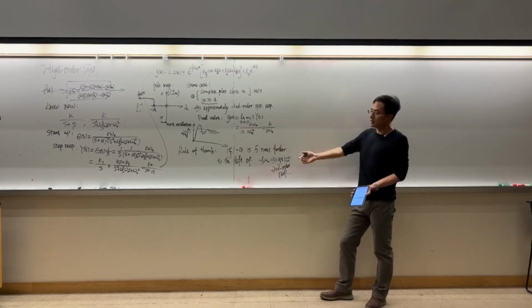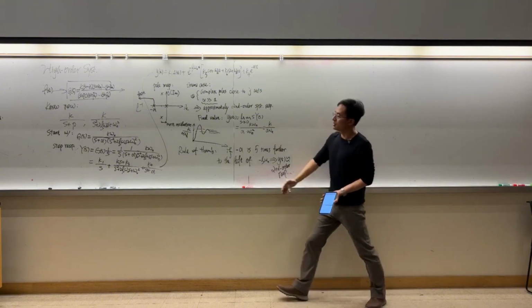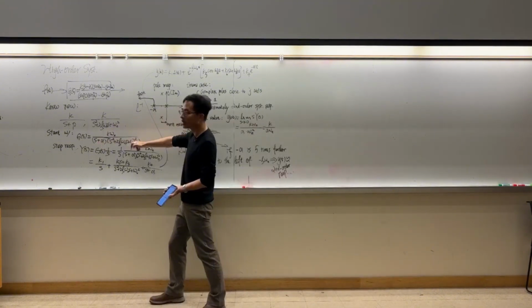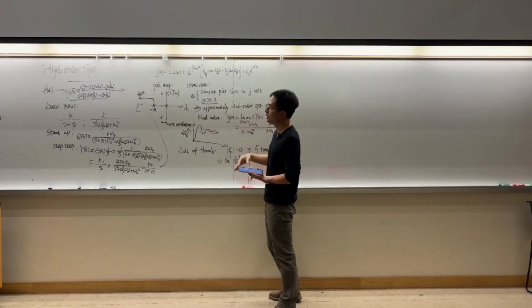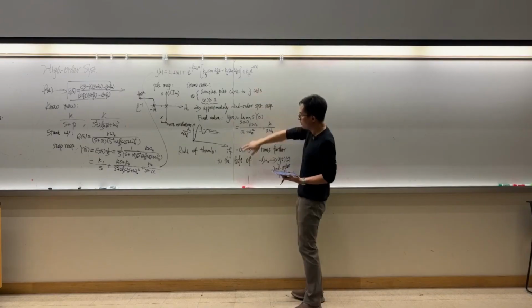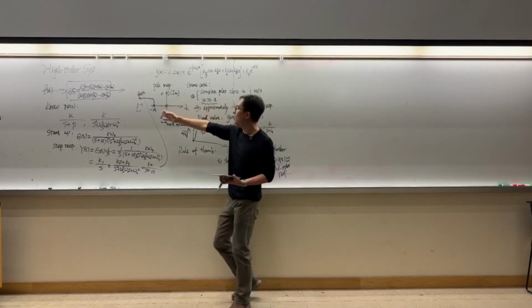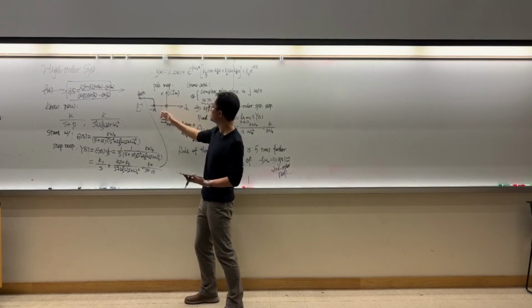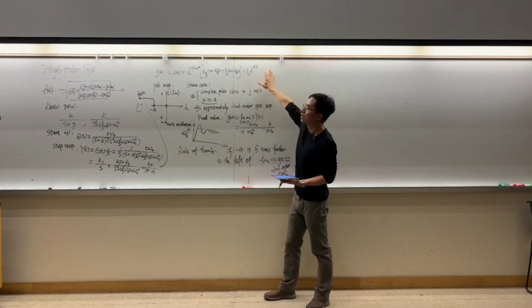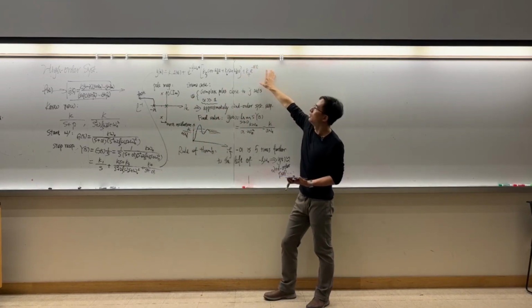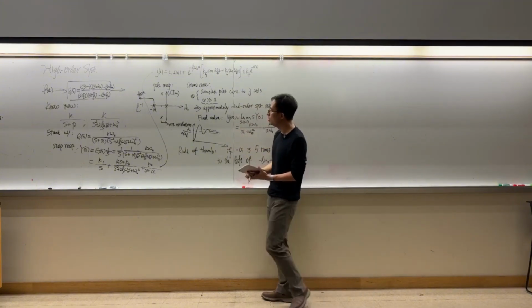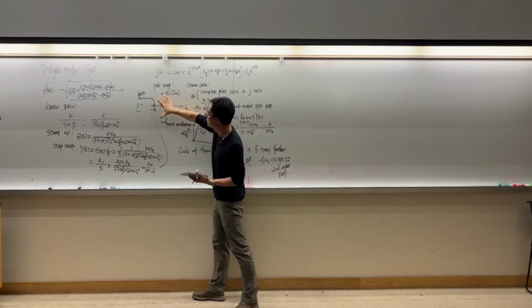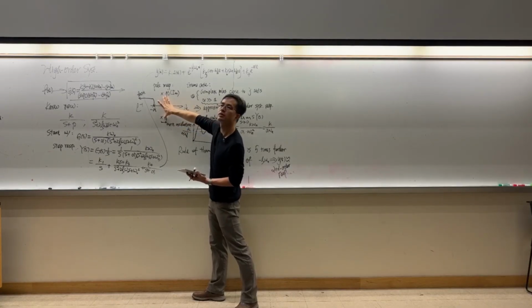So in practice, you can very easily check the locations of the poles and know the system response. If alpha is relatively closer, then the response will be a superposition of different modes together. In this case, we call the poles that are closer to the imaginary axis the dominant poles of the system.